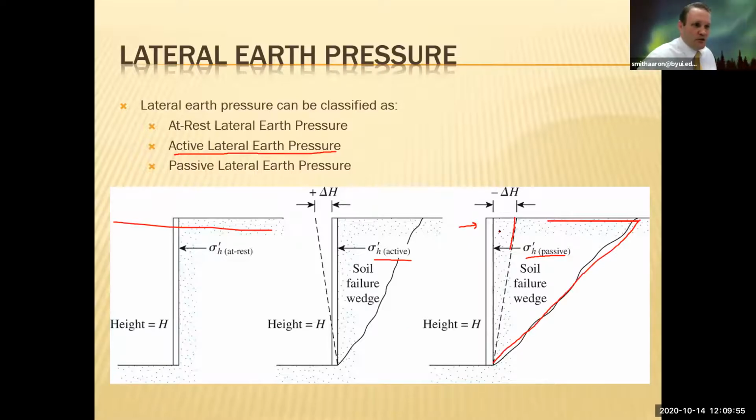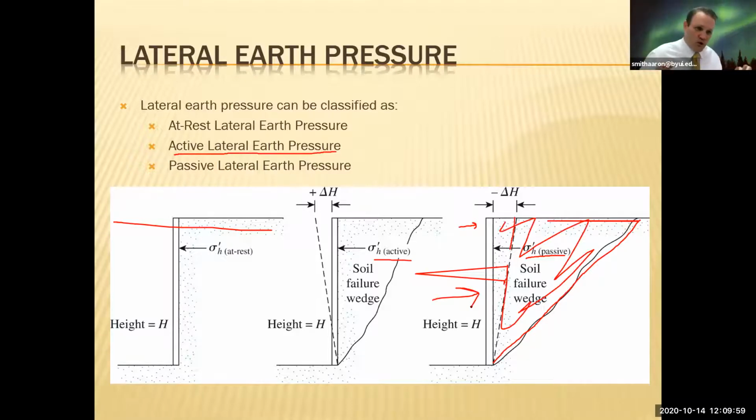And it's going to be pushing this whole wedge of soil. If you're at this arrow and you're a bulldozer and you're pushing, it's going to fail and it's going to bulge up over here. And it's a lot harder to do that. So your KPs, your passive coefficients, are typically much, much higher, an order of magnitude higher than these active coefficients.